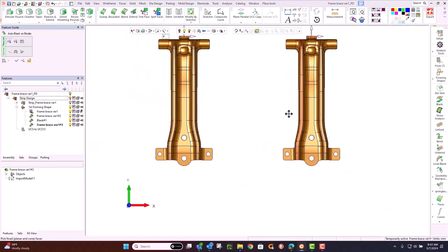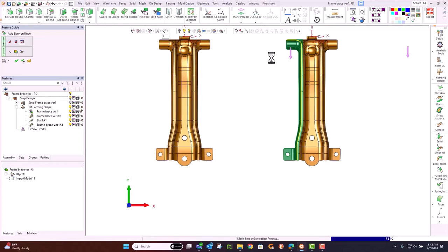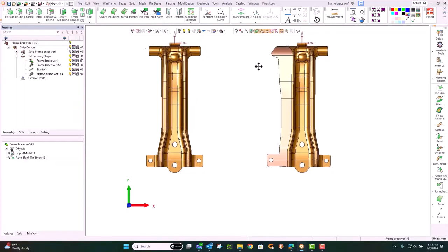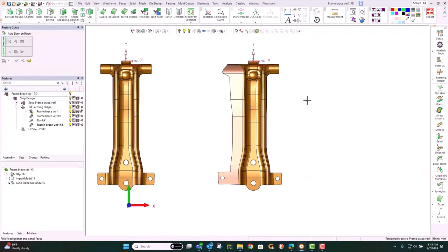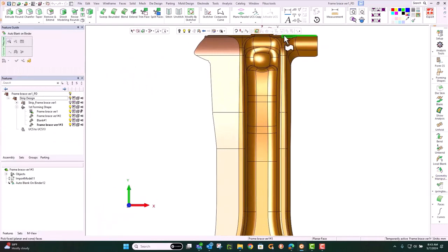It applies the material properties when it comes to the unfolding of that flange, and it'll keep the flange anchored to those faces that we picked initially, like you see here. So quickly it develops out in just a matter of a few seconds. Going further, we'll do the same to the opposite side, and we consider that one station where we're doing the unflanging on both sides.